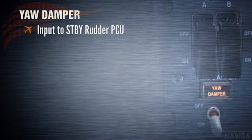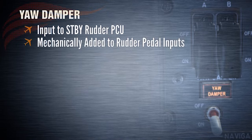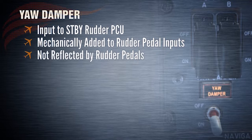Yaw damper systems give input to the main and standby rudder PCUs via valves and actuators. The yaw damper actuator input is mechanically added to rudder pedal inputs. Both inputs may move the rudder PCU piston and the rudder. However, rudder input from the yaw damper is not reflected in rudder pedal deflection.